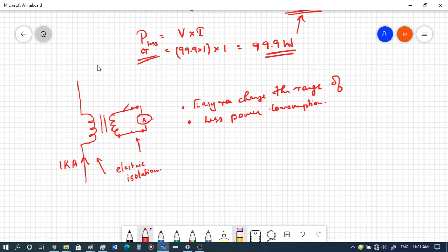You can sense the current and the voltage and everything, and that is a much bigger advantage in comparison to the general connections of the voltmeter. If you have to connect a voltmeter to a circuit, it is a bit more difficult connecting it to the primary of the circuit, but since you have electrical isolation using this transformer, it would be much easier. I hope this is clear.